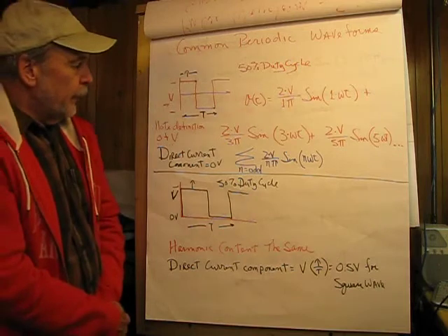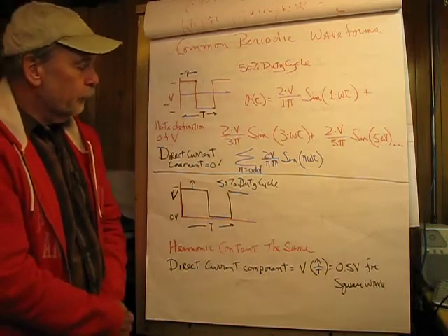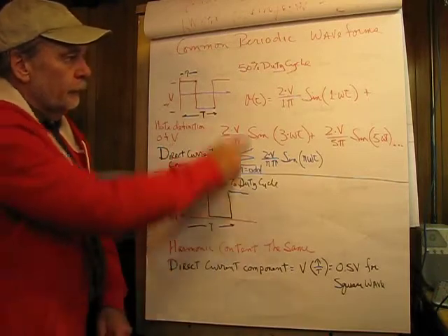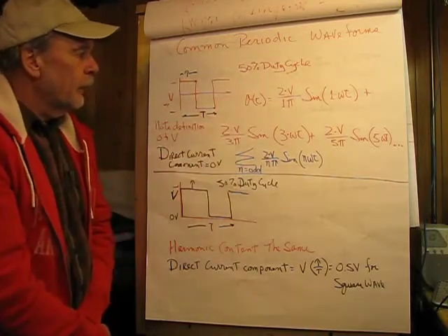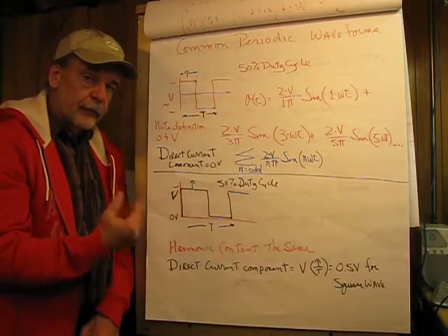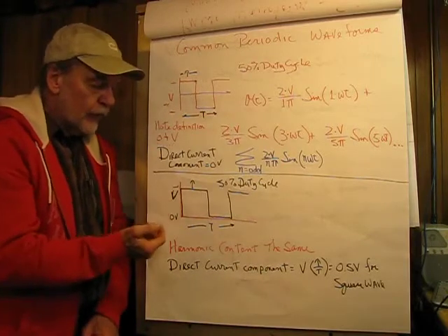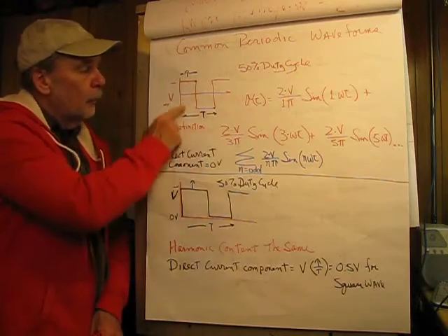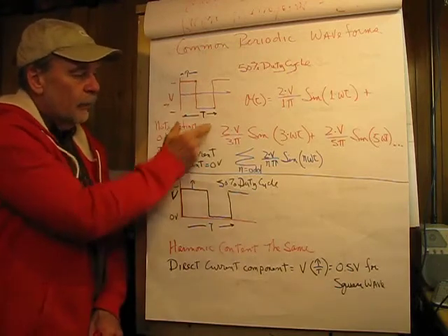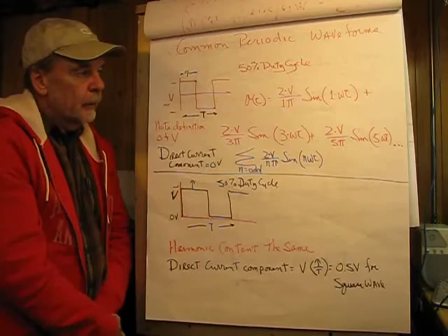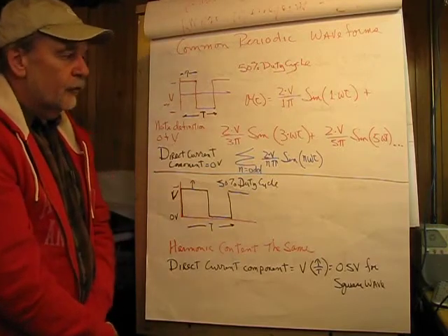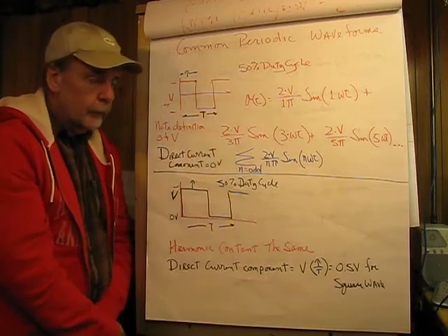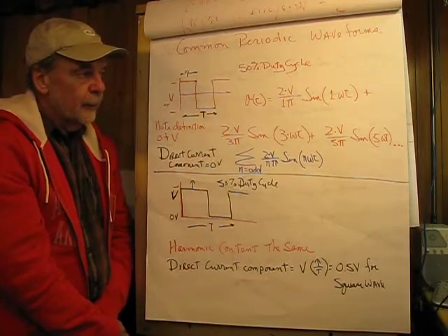To determine the duty cycle, and this is where we're going to start here, 50% duty cycle, it's simply equal to the active time. In these examples, I'm going to let the active time be the time high, abbreviated by tau, divided by the period. So if we wanted to analyze this waveform, and you've seen the v of t notation before, evaluating sine waves, this is a little bit more